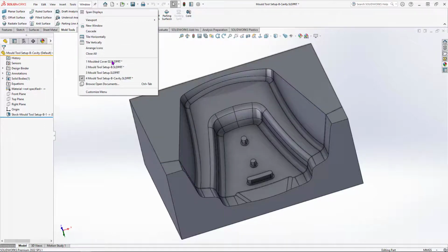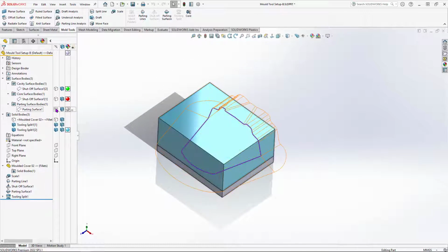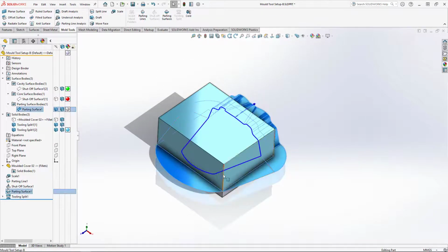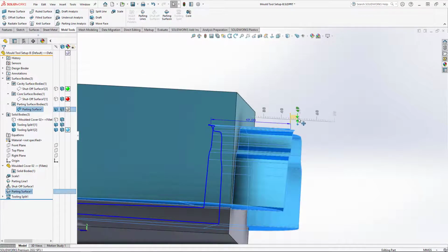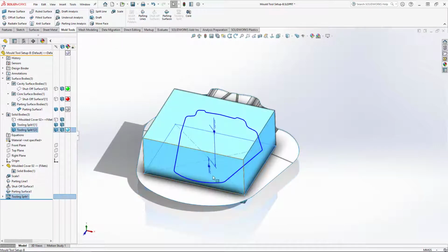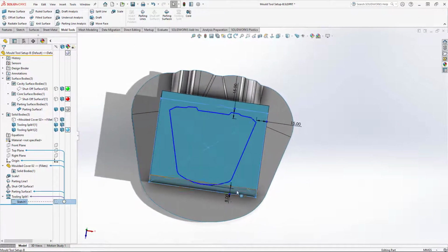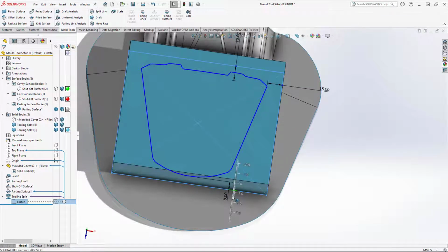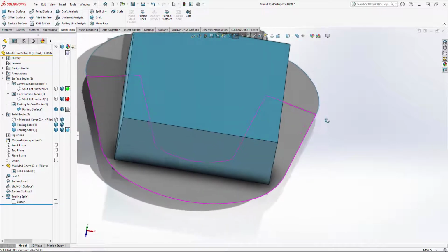So just to finish things up here, I think I said earlier I was going to extend the parting surface slightly. So if I just double click on that, I can see the value that I extended it by. I'm going to go a little bit further, just so that I can increase the size of this block if I require it. So where's the sketch that controls that? There it is. So that 8mm at the front can now be extended outwards to 15 to match all the other sections of the mold.